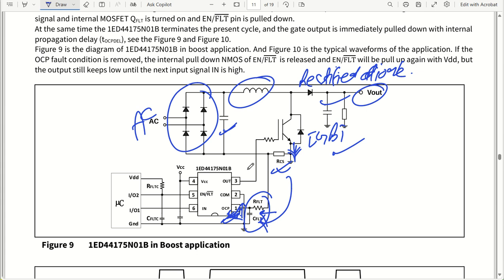The other part you can see, we have the VCC supply, and we have the enable pin that is going to get enabled by my microcontroller supply voltage itself. And this is IO, which is going to give you the output as the fault pin also. We have a pull up resistor because the fault pin is an open drain pin. An open drain pin must be pulled up to the microcontroller's voltage logic level. You should not connect it to VCC because VCC may be 15 volt.